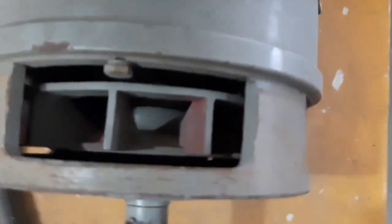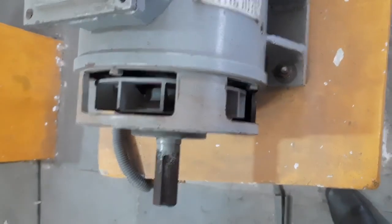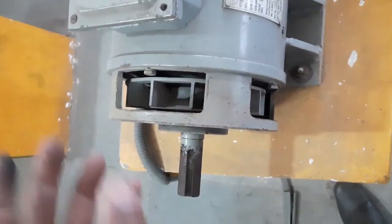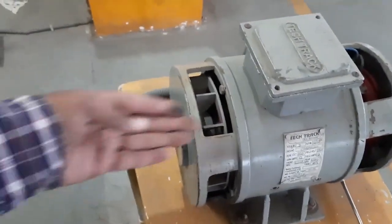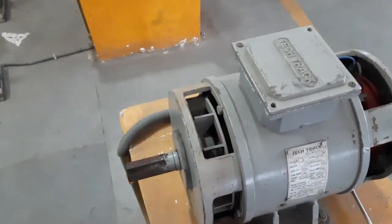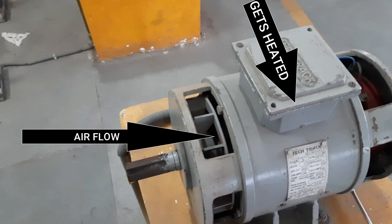As you can see, there is a fan inside the generator. This fan is usually used to maintain the perfect airflow inside the generator. The air will come from the outside of the generator and go inside in order to cool the windings. Generally, the winding inside the generator gets heated because of electromagnetic field stress. In order to reduce that heat, we use a fan which maintains the airflow inside the generator.